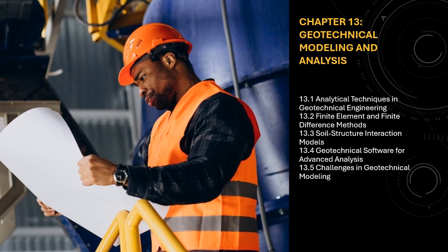It is used for a variety of geotechnical applications including foundations, slope stability, tunneling, and underground construction. Key features: 2D and 3D finite element modeling capabilities. Supports advanced soil models such as Mohr-Coulomb, hardening soil, and soft soil creep. Dynamic analysis for earthquake-induced loading and soil liquefaction. Integration of data from geotechnical investigations and laboratory tests. Visualization tools for easy interpretation of results.